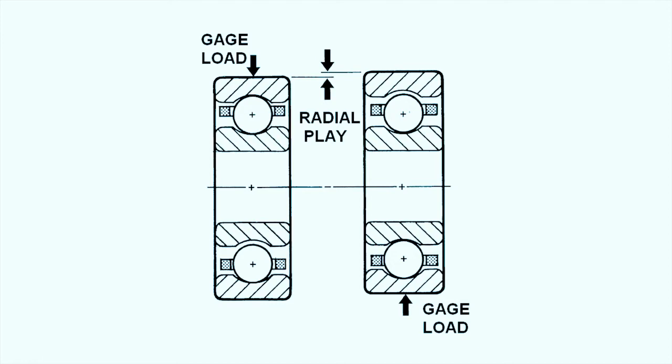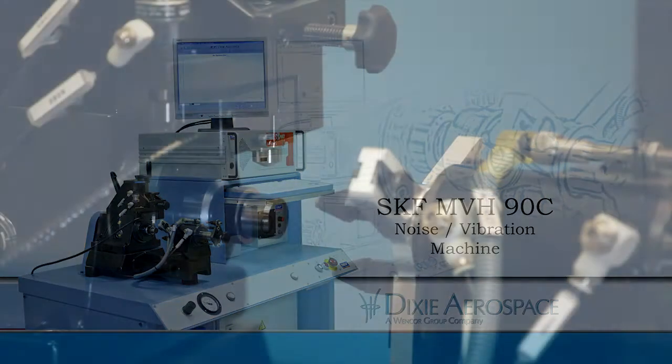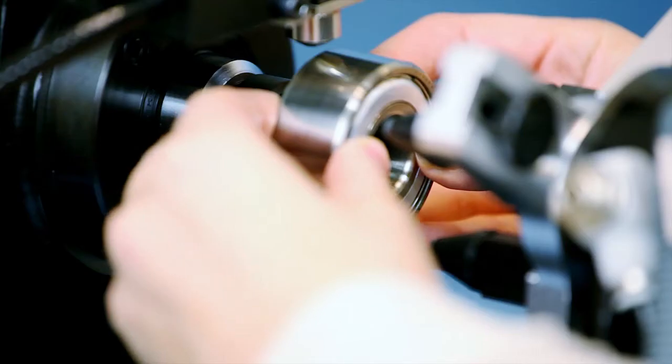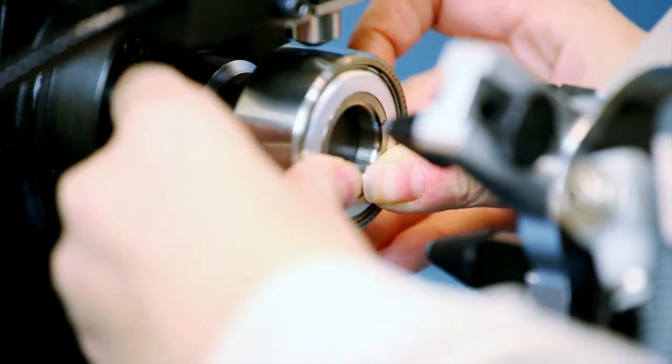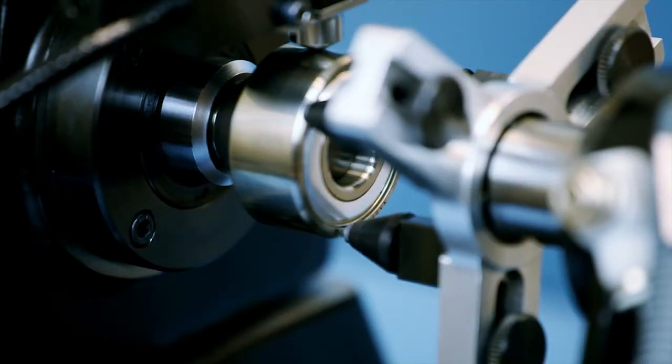The bearing analyzer is a machine that Dixie uses to simulate an in-operation test condition. This machine will collect a noise vibration signature from the bearing by the use of a high-sensitive ruby-tipped microphone that is placed on the outer diameter of the bearing. The engineer places each OEM bearing on the shaft spindle and then applies an axial force on the rings so no radial play is remaining.